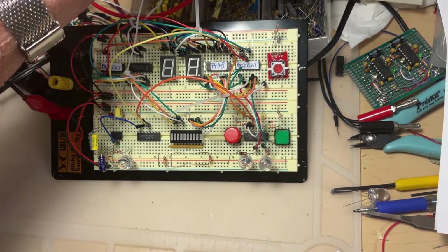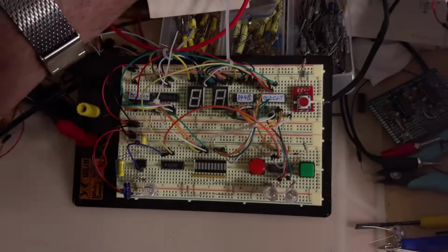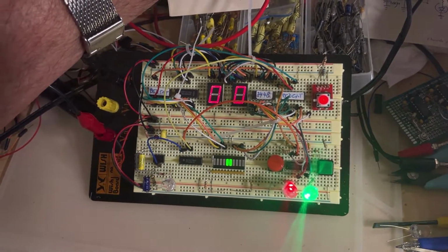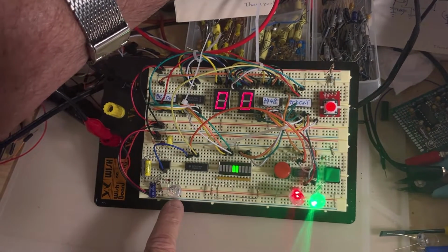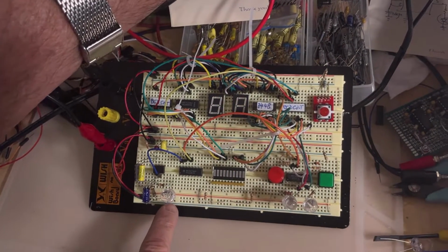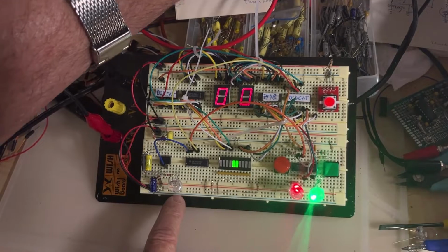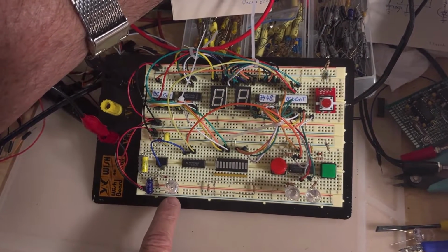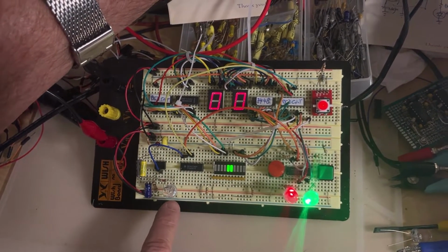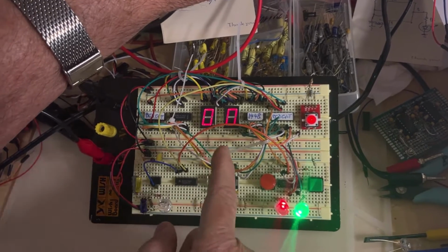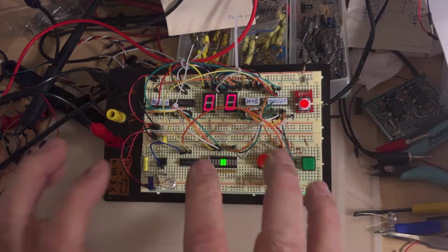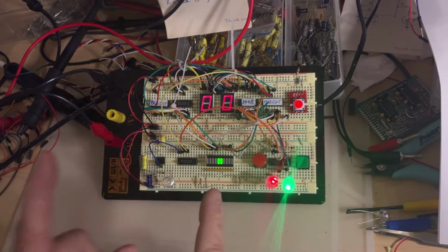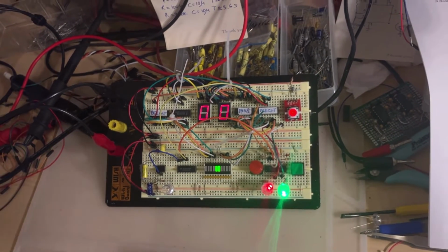So we take a look. When I put the power on, the duration is very short now. You see? It's about 1/10 of a second. You almost have no time to press any button. But what you have to notice, the counter is always starting from 0. So that was a nice application of power on reset. How do you do this? With one monostable circuit. Okay?